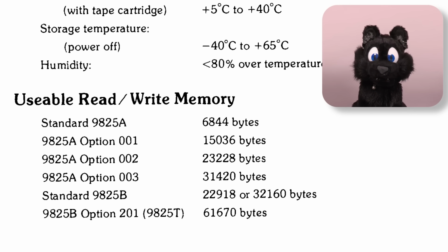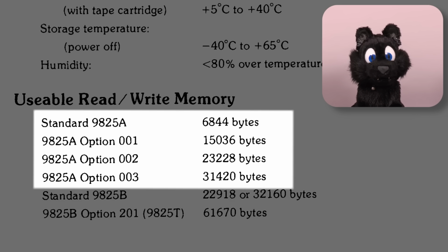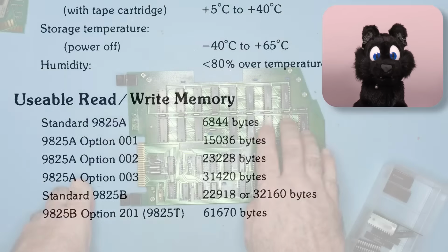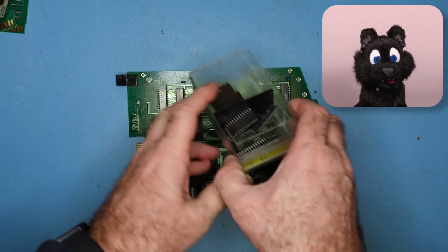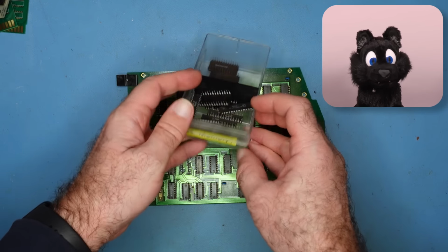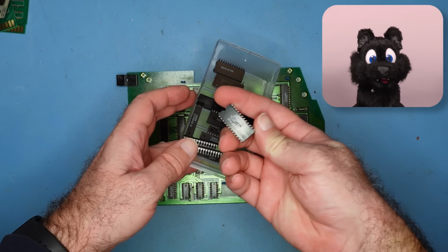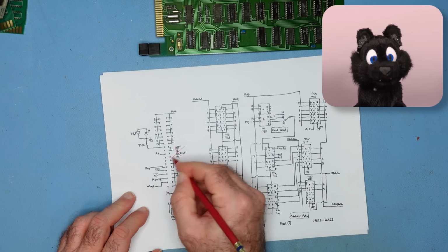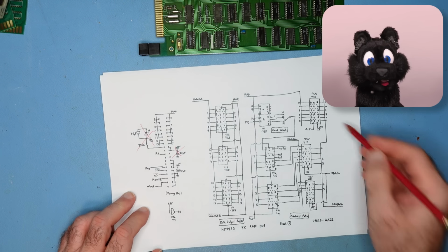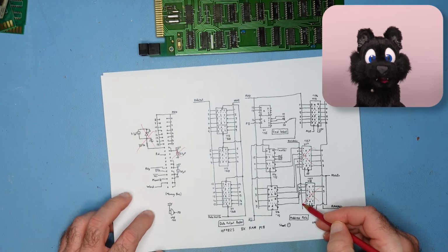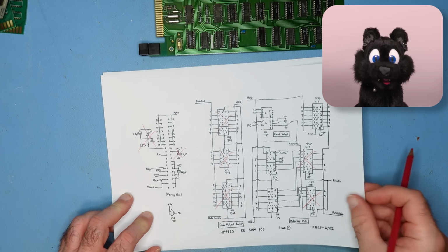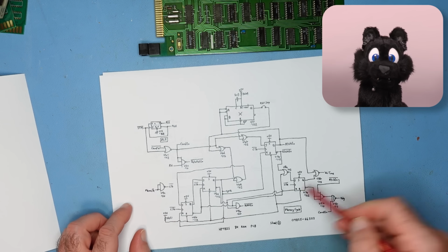But then I thought, it's just 32K of RAM, or 2 times 16K chips for these at maximum. Why even bother to use DRAM? Back in the day, SRAM of that size might have been too expensive and power hungry, but modern chips? Surely a few SRAM chips would be easier to implement, no refresh cycle needed, and modern chips have 5 volts all around and no inversion on the data. I could ditch about half the circuitry.